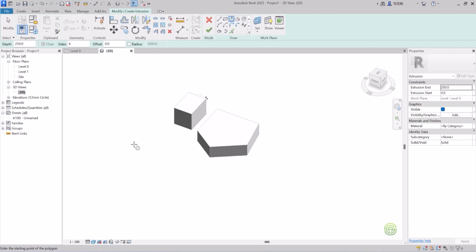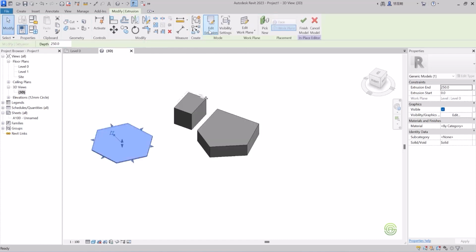And as we have six sides, I just select this tool, inscribed polygon, and then I will click and just move your cursor to give a radius. So now I'm giving 8,000 radius randomly, or you can just give any radius as you want. Now after deciding the radius, just give a second click. You have created the 2D shape. Now to change this 2D to 3D, we have to click on the green tick. Once we click on the green tick, we get these control arrow points. So just select any arrow point to extrude it like this.